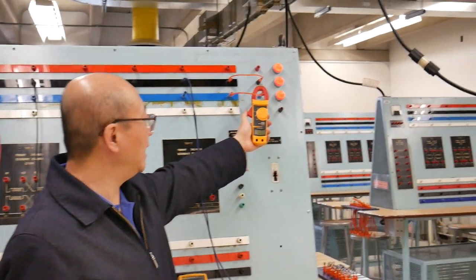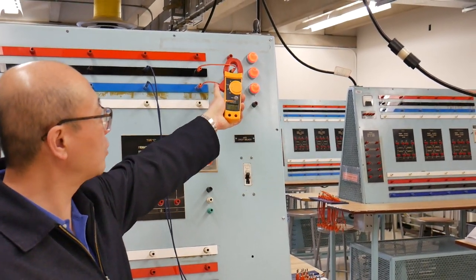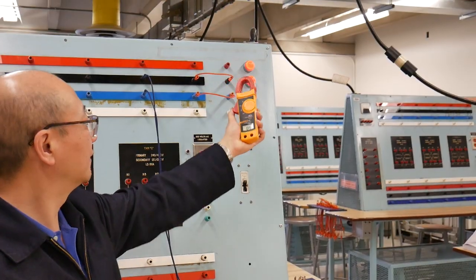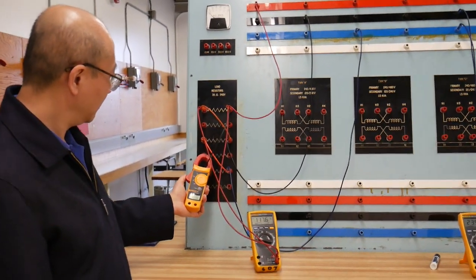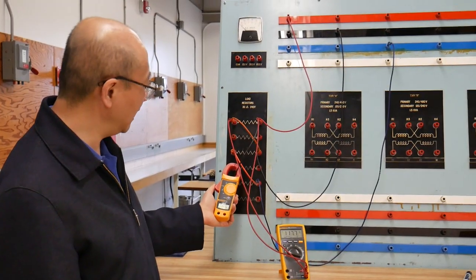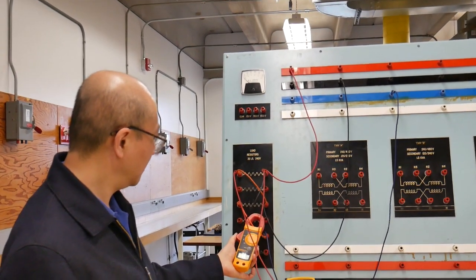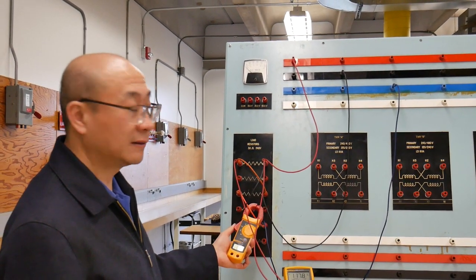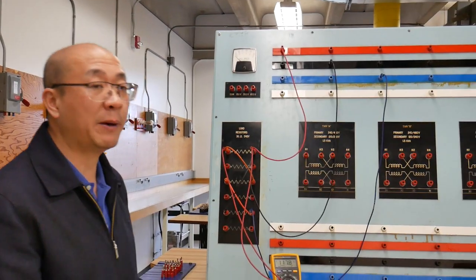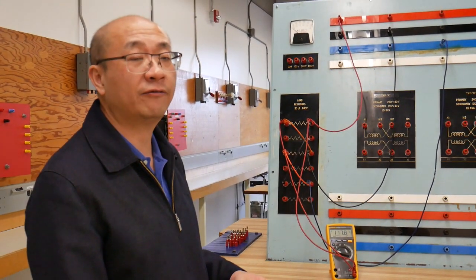My line current is 11.1 amps on both of the lines. And the current through the phases, one of them is only 3.6, another one is 7.5. So if we calculate the power, in an open line situation, we only have 50% of the original power.